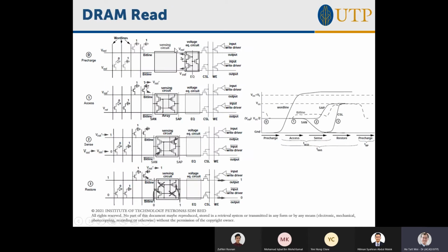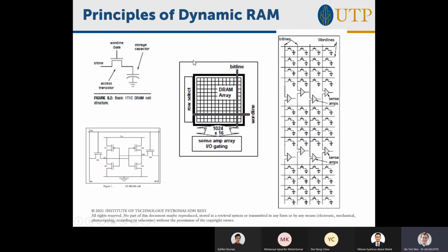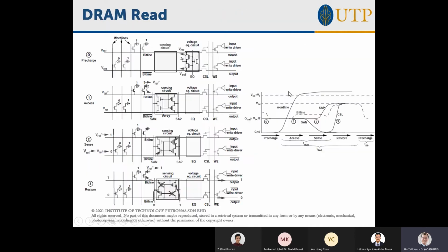There's a bit line pair, and it's going inside the sensing circuit, right? Because this is the sensing circuit. It's called the sense amplifier. And you remember that the sense amplifier has 2 roles. One is to bring the small change in voltage here to the full logic, and number 2 is to buffer, to actually hold and remember this value.